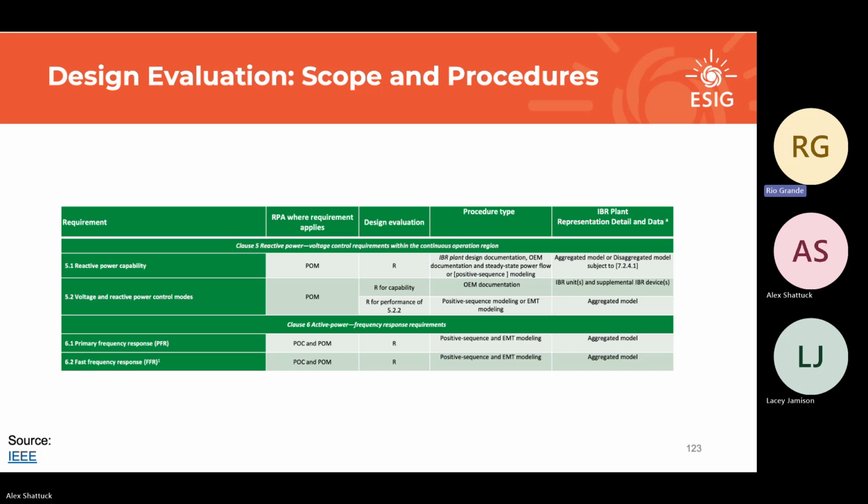Much less contentious, PFR and FFR. You don't need to disaggregate anything, right? The frequency is the same throughout the plant. It's fine to do in positive sequence and EMT modeling because it's aggregated. There's basically no discussion or argument on this one.